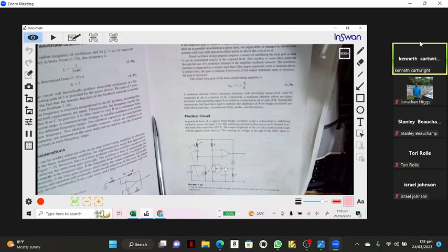When this voltage is low, the gain is high to begin with, and when the oscillation builds up, there's a DC voltage here that's now higher, which causes the drain to source resistance to be larger.